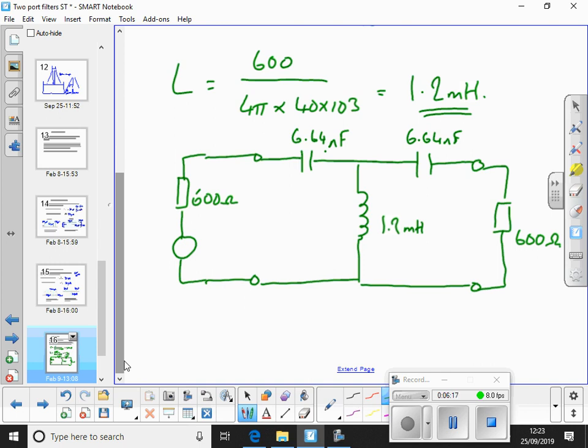Not wholly, because those two should be exactly the same. If they're not exactly the same, then you're not going to have the same input impedance as output impedance, so it is going to cause some kind of problem. But tolerances could pull the results back into line, or it could make it worse. Depends.